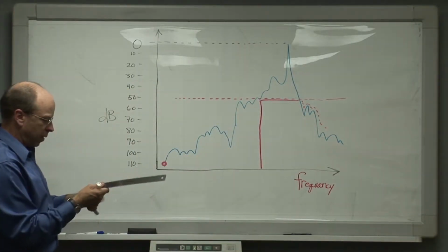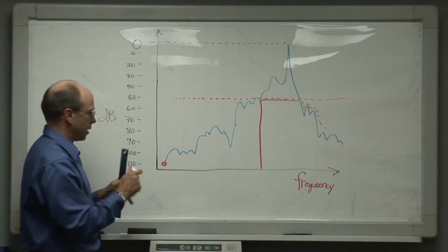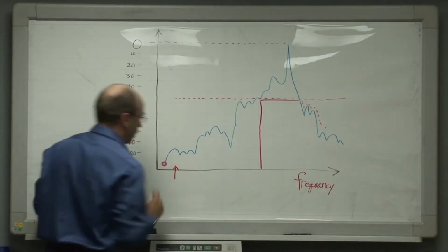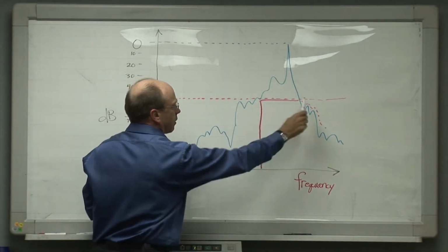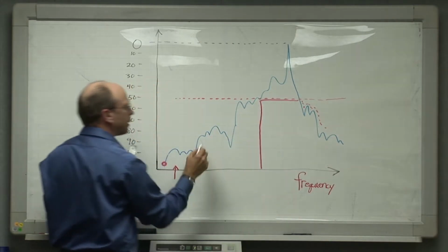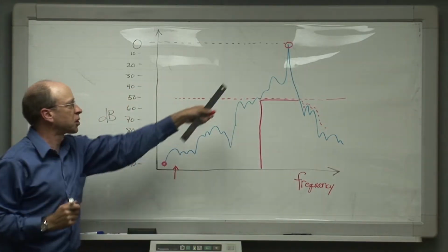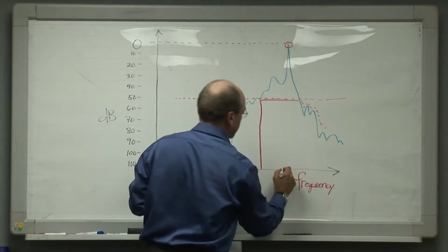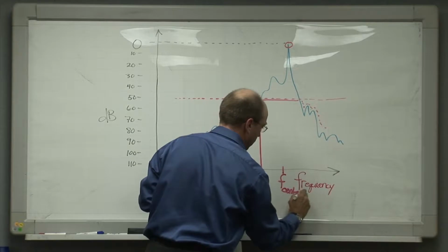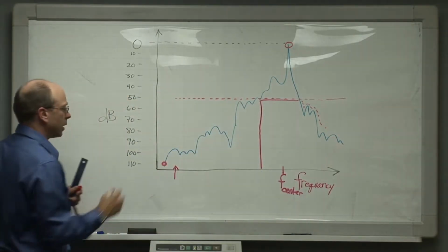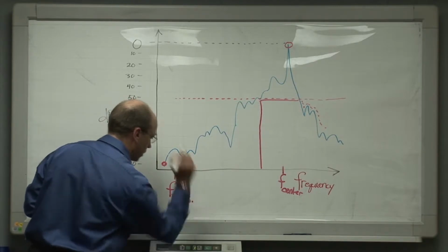But initially the problem is that if we're measuring these emissions down in here at, say, this frequency right here, not only will we be saturating in this part of the spectrum when we try to do the swept spectrum measurement, but this power level here will actually be saturating the spectrum analyzer at this frequency, F sub center, like so, even though we're trying to measure out here at F sub mes.